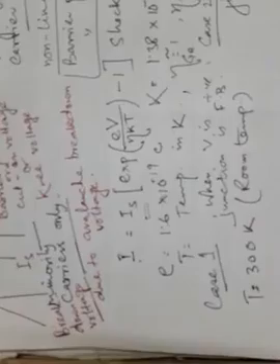Now if we take T equal to 300 K, that means room temperature, and if we substitute all these values in this particular equation, then I can be written as Is e to the power 39V by eta, minus 1.